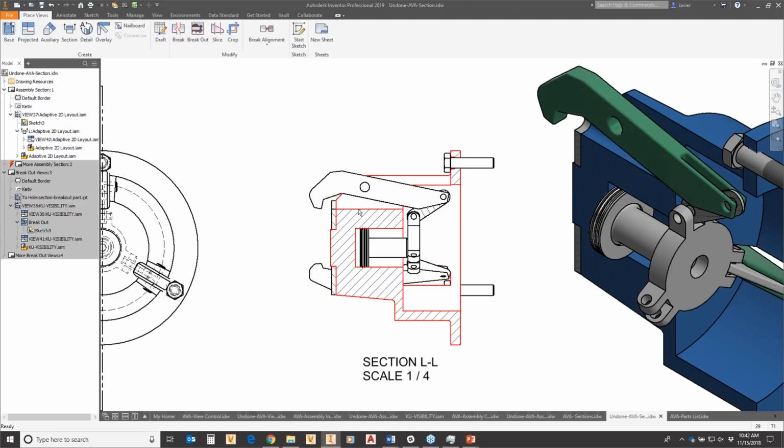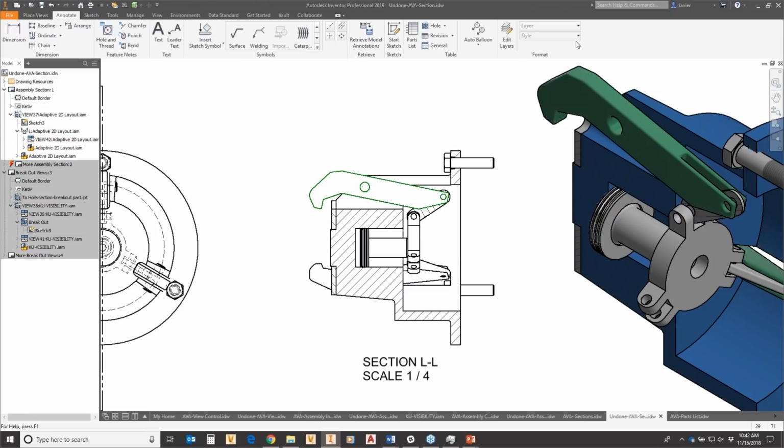As I'm moving along here, here's another option you have in terms of selecting parts. When you select these components, these all get assigned to layers automatically, visible edges versus hidden edges, you name it. If you ever want to just change or highlight a part, you can right click and make sure you're set to highlight the entire part. We can select it, and on our annotate tab, it should show you what layer that geometry is on. And so it should make it easier to do that.